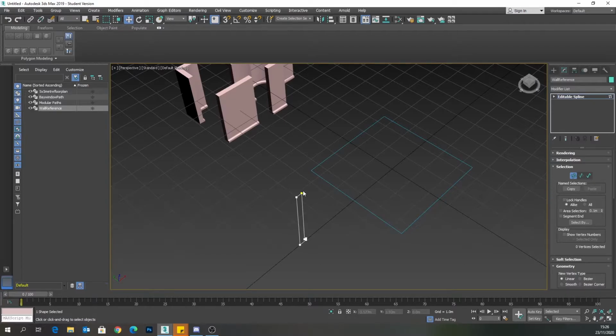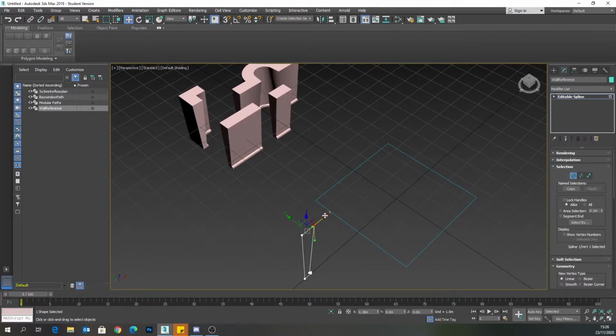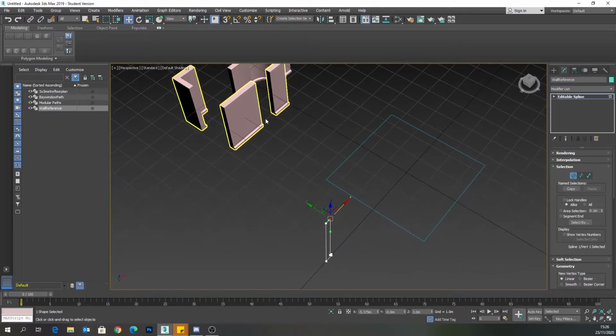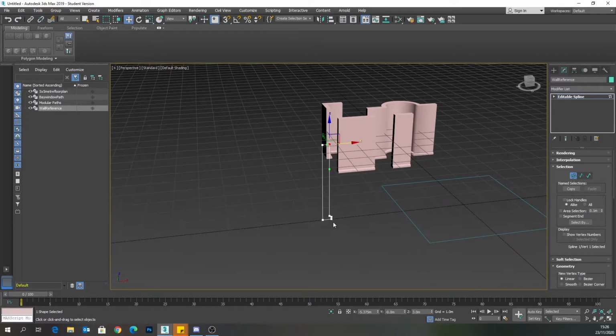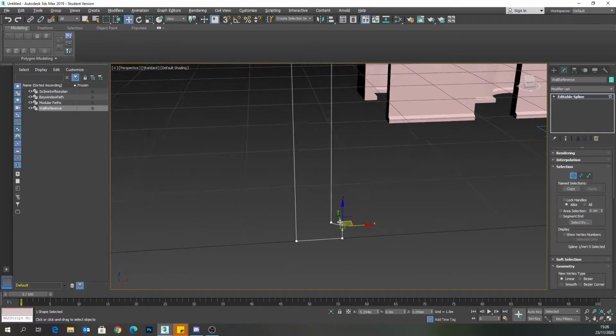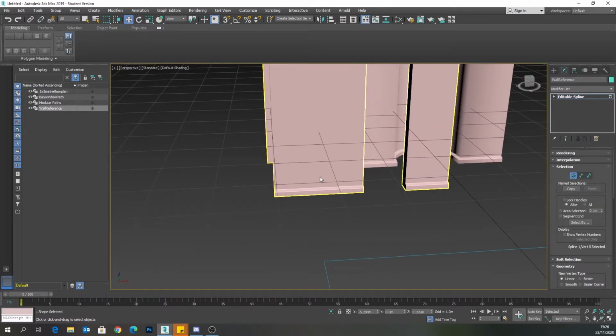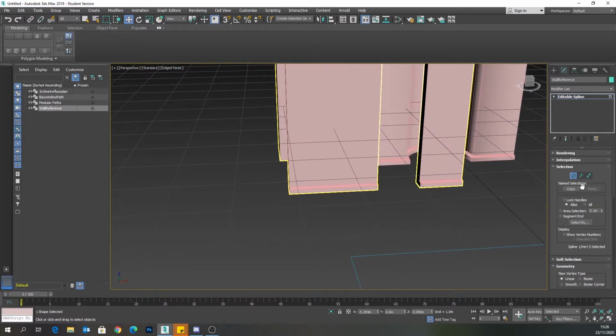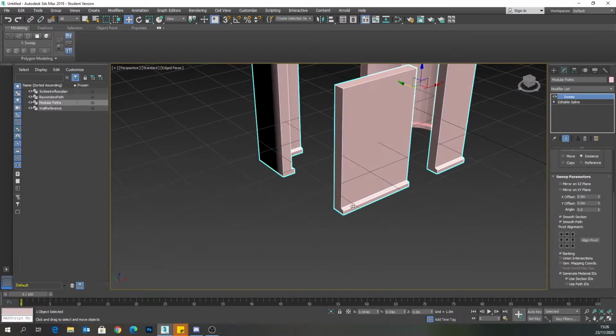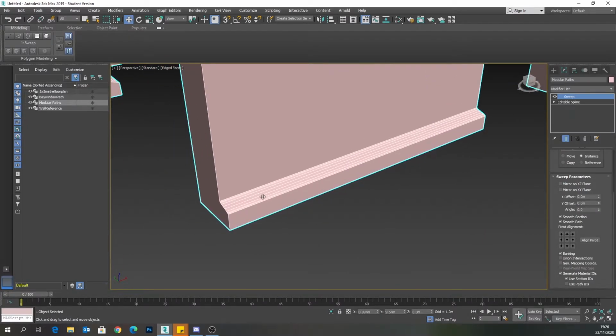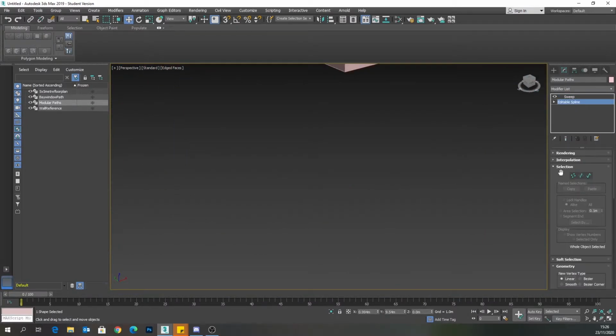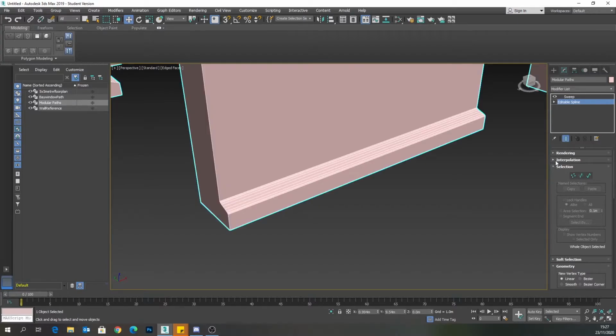You apply as many sweep modifiers as you like, just bear in mind that now we can work on them together and still use the reference shape. So now I can continue to do some of the editing to that. Now, one thing worth considering is the interpolation. As we can see, it's putting a lot of edges in there. And if we want to see the end result, we click that there.